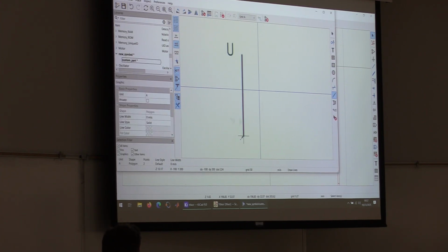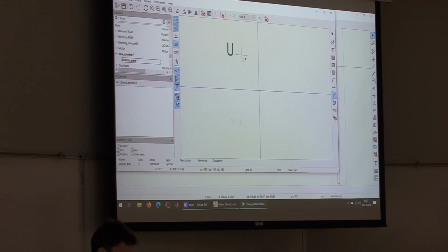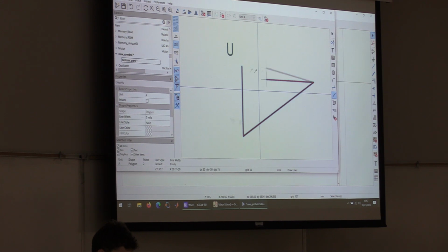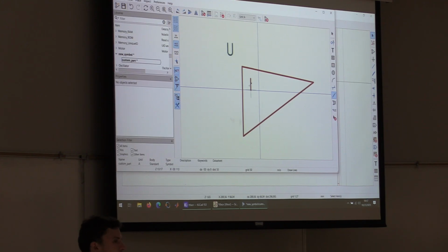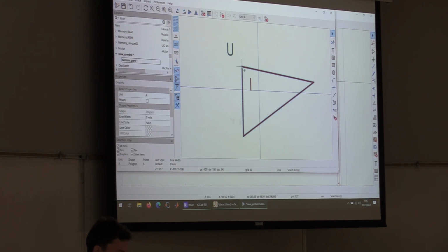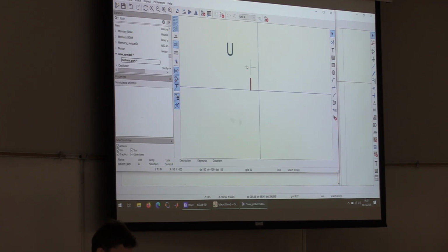I'm not going to try very hard, but you can draw and, oh, this is going to be a lovely op-amp. For those of you who have seen an op-amp, this is going to be a disgrace to every op-amp ever. Okay, actually, you know what? The drawing can be finicky if you're not used to it. Another thing too is if you're drawing and you're annoyed with the grid, you can change the grid size. And I am in mils.